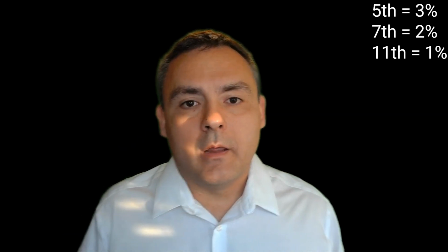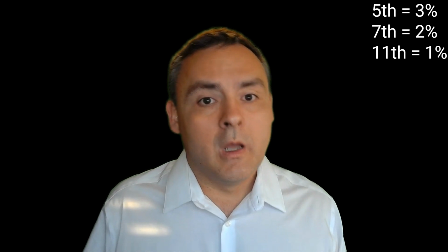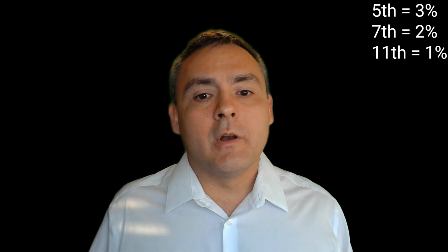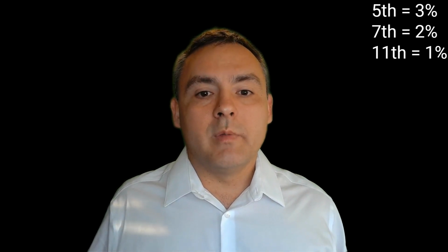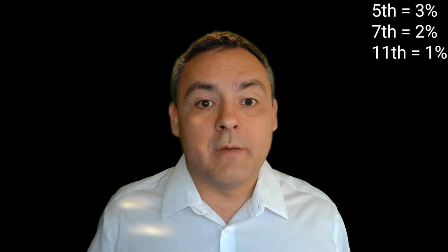We're going to look at three harmonics, which are extremely common ones. We're going to look at the fifth harmonic, which will be 3% of our fundamental. We're going to look at the seventh harmonic, which will be 2% of our fundamental. And we're going to look at the 11th harmonic, which will be 1% of our fundamental. These are just arbitrary values that I've picked for our example. They're quite representative of an electrical system with low harmonics.